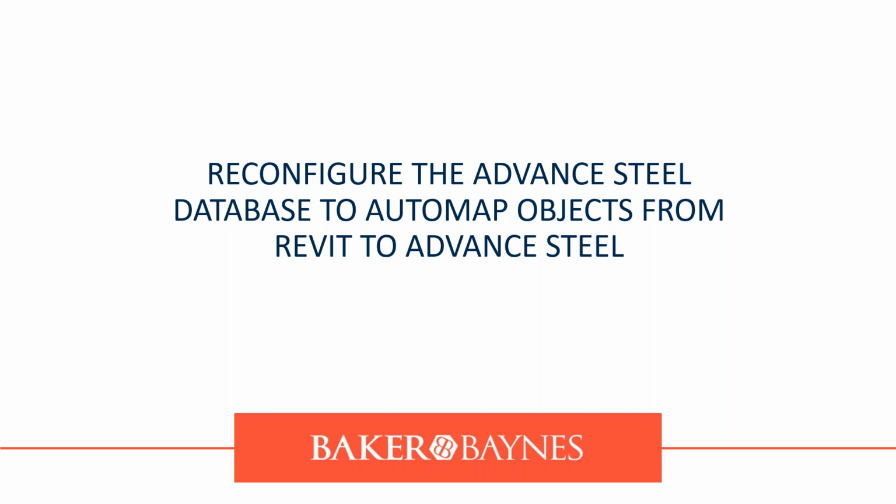Advanced Steel works with a database. Now, that database, because our sections are very similar to the UK steel profiles, uses a numbering system. So if, for example, a UK I section or IPE is in the database table numbered at item 160, and the I section for the South African one is numbered at, let's say, 200, the database will read the UK section first because 160 comes before the South African steel sections.